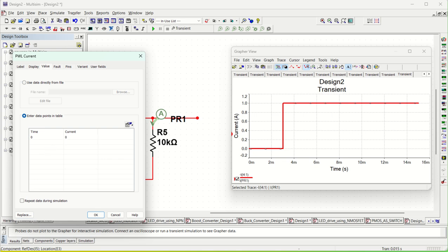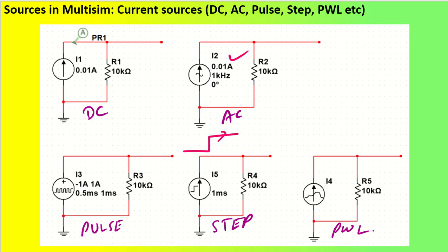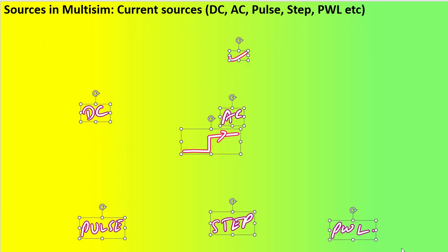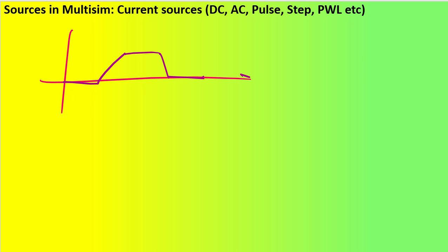Okay. So let us say my current source will be something like this. Let me give an example. So I'm going to take example quickly. For piecewise linear function, I am going to define my current sources to be this. Let's say it starts 0, then it starts up and then down and then 0. Like that, this is my time in millisecond and this is my current in, let us say, milliampere.